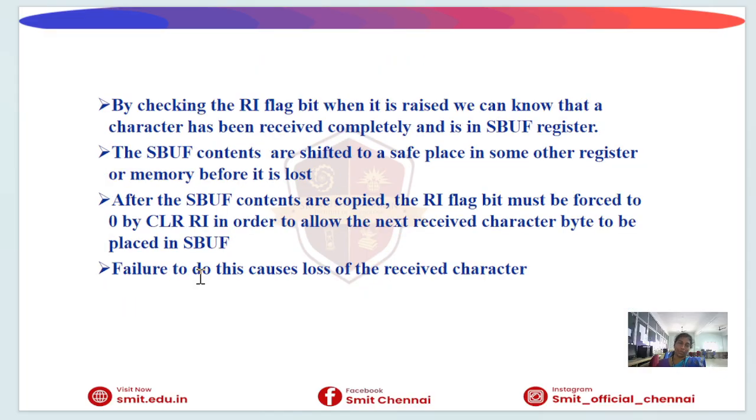Why is the RI flag important? It prevents the loss of received data. Once RI becomes 1, as we already said, the programmer must immediately copy the contents of SBUF into another safe memory location. After copying the data, the RI flag must be cleared. How should we clear it? Using the instruction CLR RI. If RI is not cleared, the next incoming character cannot be stored in the SBUF register, resulting in data loss. So the programmer's handling of RI is essential for reliable serial communication.